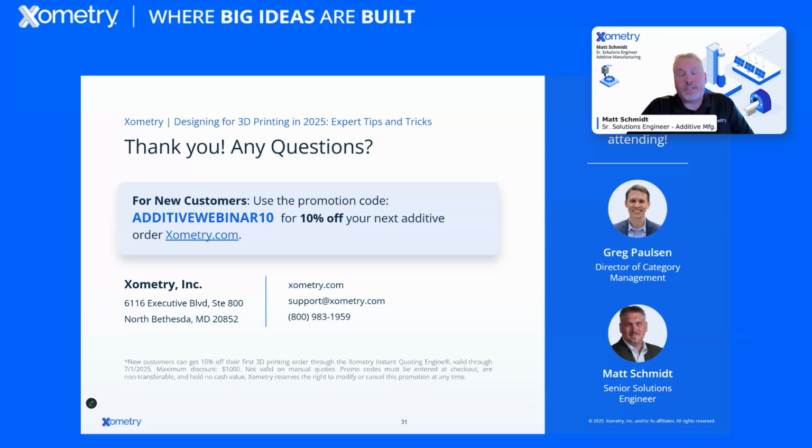So with large parts, that's a huge cost savings when it comes to printing one large part versus smaller parts. You will have less material volume going into that one part, so your cost would be less there. And then also, of course, you've got less labor in post-processing each individual part rather than one large one.